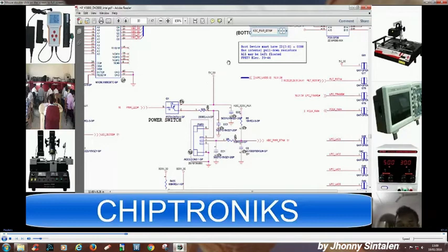So by seeing this circuit diagram, we can say that first the KBC power button signal would go to the EC of the IO controller, and after some time this power LED will glow. That is, the power LED will not glow immediately because the input is connected to 5V_S3, and we can search from where this 5V_S3 is coming.